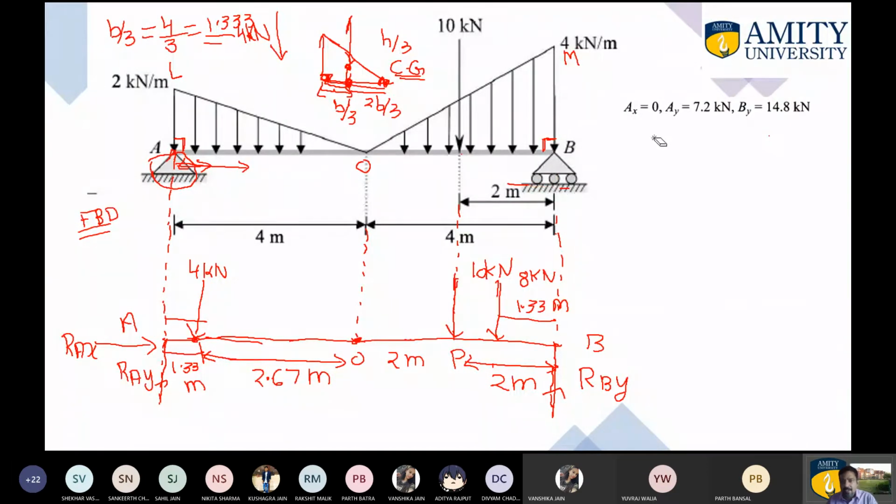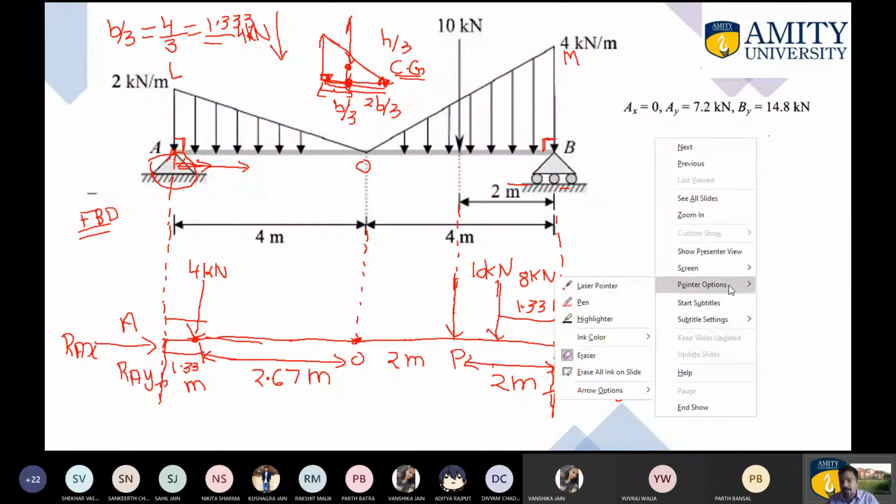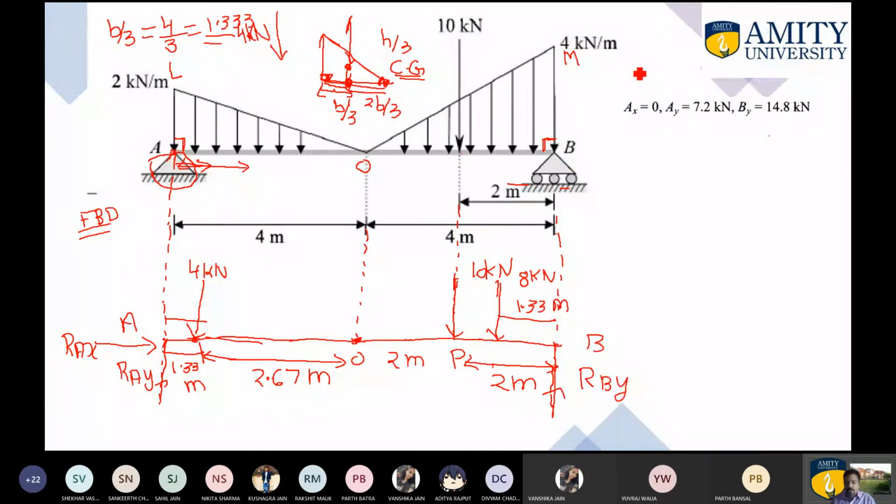Okay, as no one is having a doubt, it is clear to you all. So I am now moving to the solution. As you can observe, this particular beam is not moving in any direction, which means the beam will be considered under equilibrium as per the force system acting on the beam. As you can easily observe, this force system is coplanar, because all the forces are acting in a single plane, which is the xy plane, and the force system is also non-concurrent.